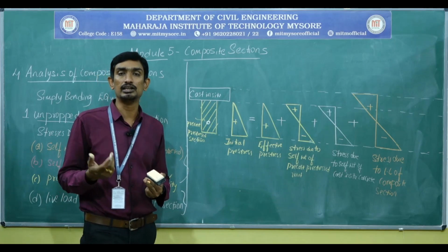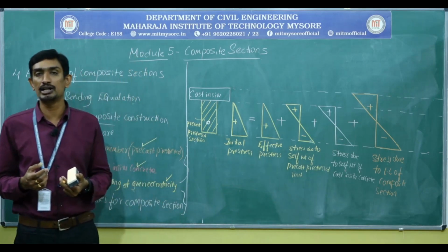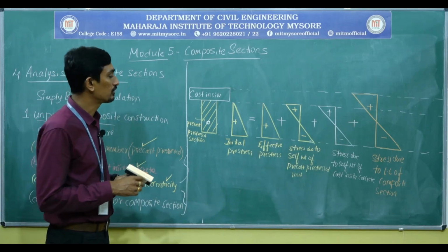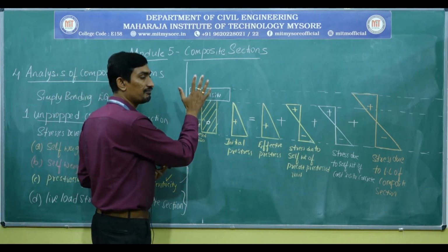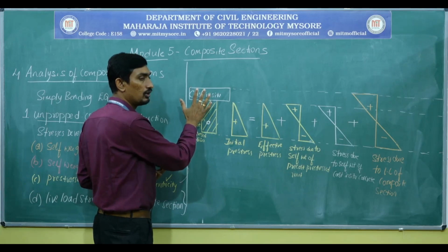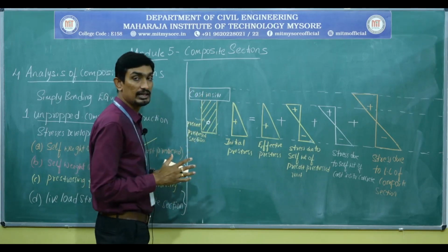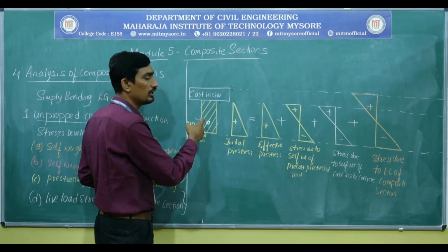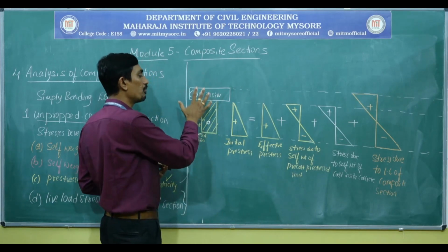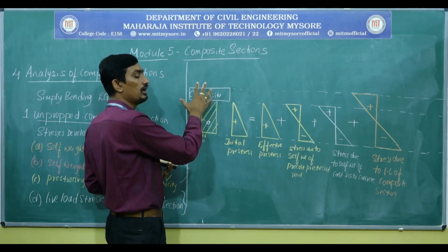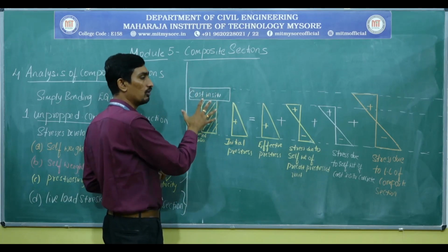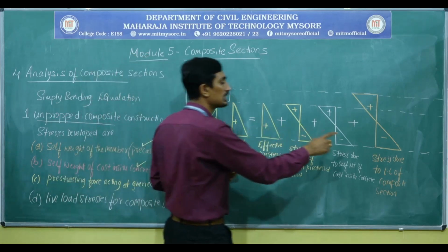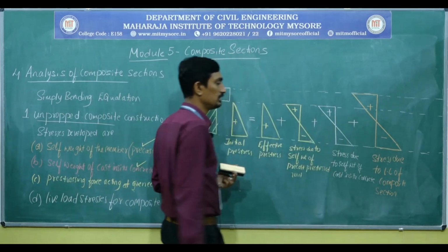As I stated, this composite section will mainly be used for bridges or highway bridge decks, so till it functions as a monolithic unit, it will not be subjected to any live load. So once this composite section hardens, it will be subjected to the vehicular movement or the live load. Because of that live load, this is the stress developed.